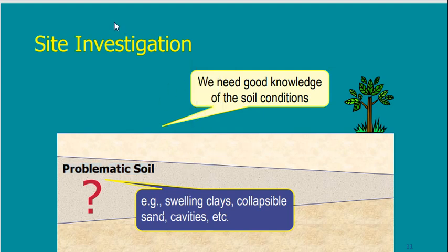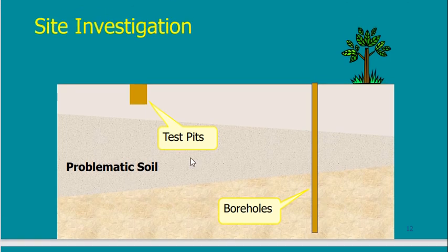So to study geotechnical engineering, I have to start with site investigation. I have to find out how we do site investigation to assess the soil below. How can I do this? I can do, as I said, just a small hole, but the problem of this small hole is that I will see good samples, but it will be shallow depth.